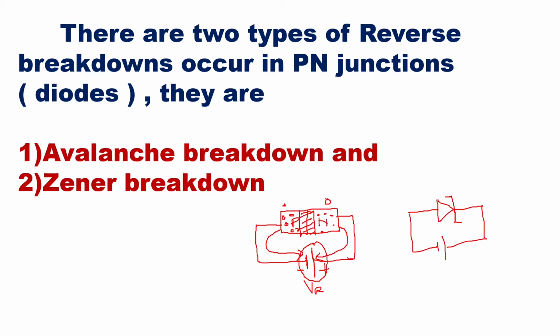Now, when you apply this voltage, if you see the graph, the third quadrant graph is for the reverse bias condition, let the x-axis be voltage and the y-axis be current. This is the reverse voltage and reverse current. We see that as you increase the reverse voltage, for some time there is no flow of current, and at a stage comes when there is a large flow of current. Okay, so the voltage at which this happens is called the breakdown voltage. This is the breakdown voltage, and this is the breakdown region, where the current is increasing drastically.